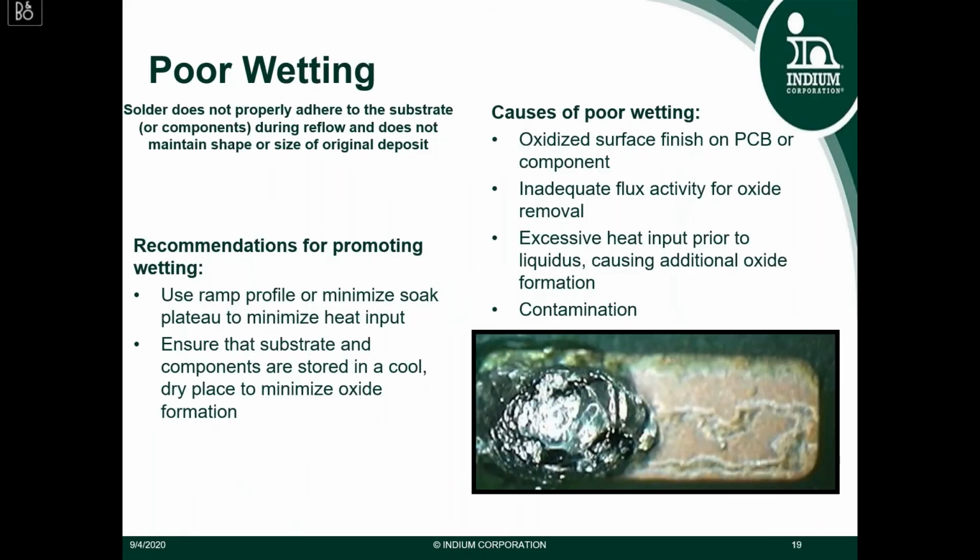Poor wetting. We talked about poor wetting a little bit in the last slide. Poor wetting is when the solder doesn't properly adhere to the substrate or the component during the reflow process, and it doesn't maintain the shape or size of the original deposit. This can cause problems for intermetallic growth or mechanical reliability.